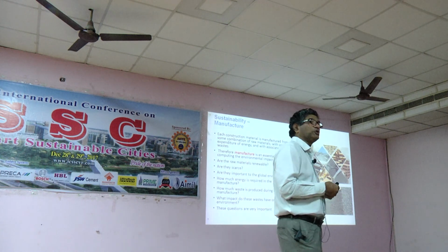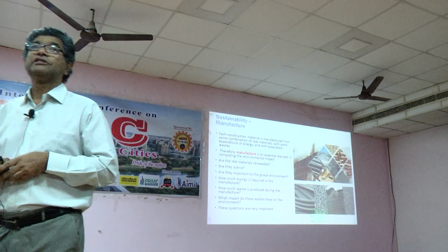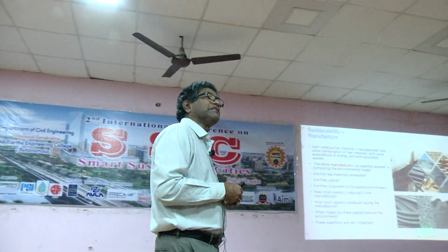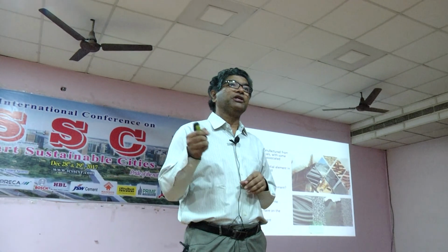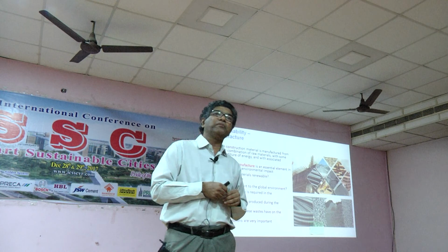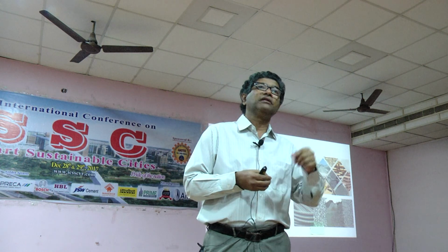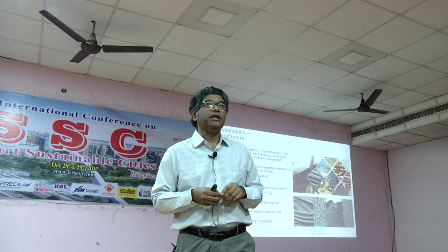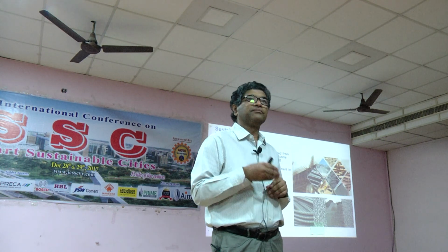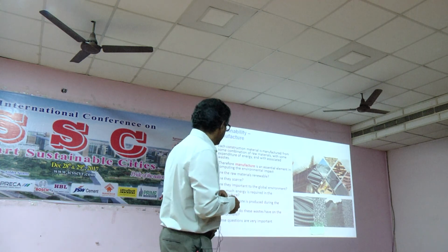Now, this morning I went to a site where they showed some cracks. Some engineers were saying that these cracks are coming because of the usage of fly ash, right? But then I asked, what is the extent of the crack? The extent of the crack is only about 3 to 5. I said, put a binding wire and see to what extent it goes. It goes only by 3 to 5 now. They said it is only a shrinkage crack due to the draining of water, the fine product being on that. It's not a real structural crack. Let's not get worried about it. But I told them, you should be very quick to start curing the element as fast as possible. As soon as it dries out, the cracks won't appear. Right? We need to find out the solution.